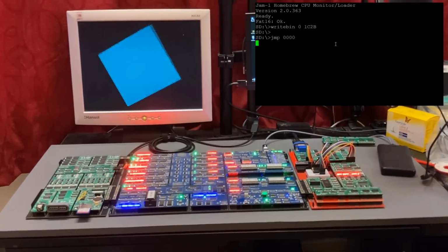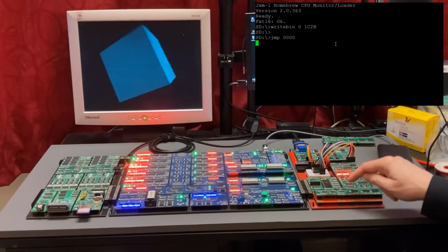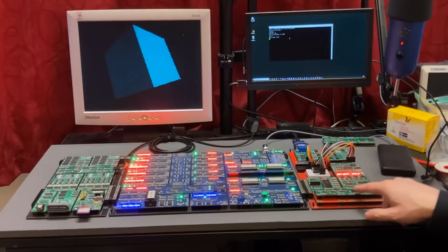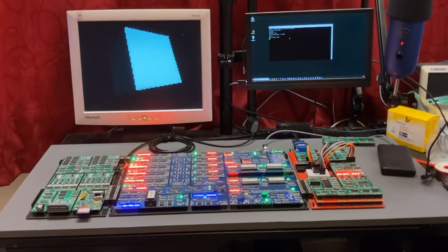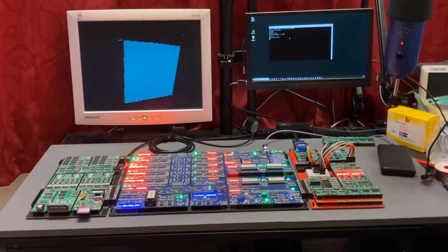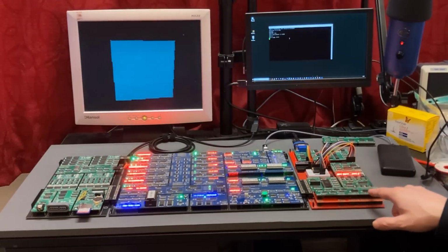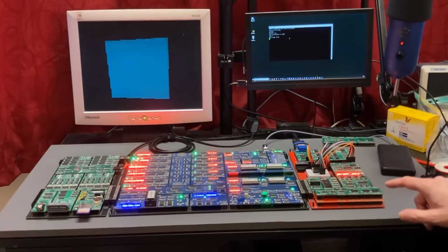Bingo. Okay, I have to say, I definitely need to pay a lot more attention to how old my solder paste is, because a lot of these joints proved a bit tricky. So I've got a couple of jobs ahead of me between videos. I'm going to need to clean this PCB because I've got quite a bit of flux on there now.